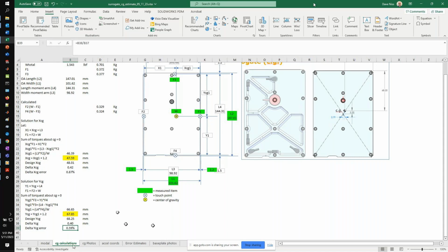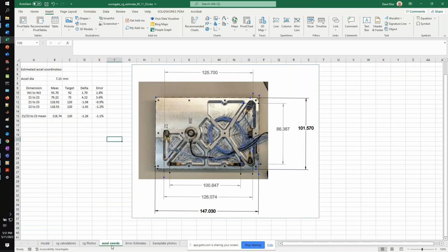Wait, you're playing the straight man to my next subject. Okay. Well, I'm trying to figure out how do we get through this, but maybe you've got an answer. So, all right. If you look at the various sources of errors, to me, the two gross sources of errors are the hardware, which is mass, rotational inertia, and where do you put the accels, and then there are the channel errors, because you're going to be measuring. And so if you look at the hardware errors, we've just looked at mass, where is the CG located?